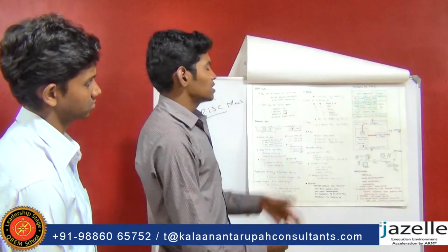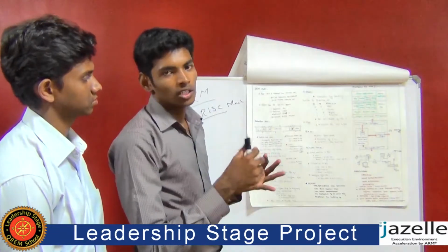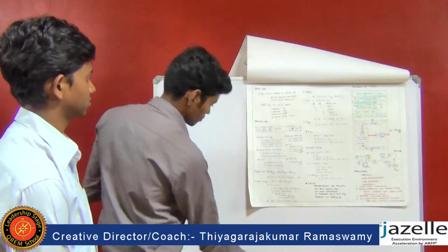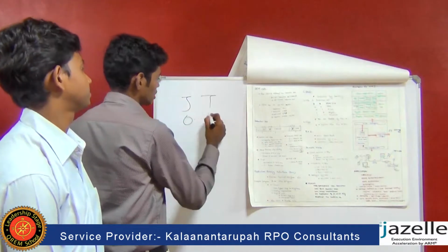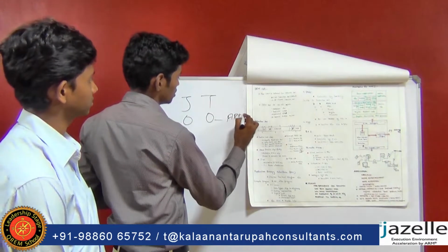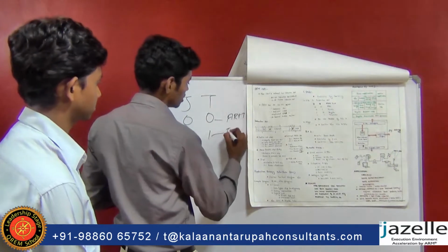Then the state is indicated by combining 2 bits in the instruction set, the J bit and the T bit. If the J bit and the T bit are both 0, the processor will be in ARM state. If the J bit is 0 and the T bit is 1, the processor will be in Thumb state.